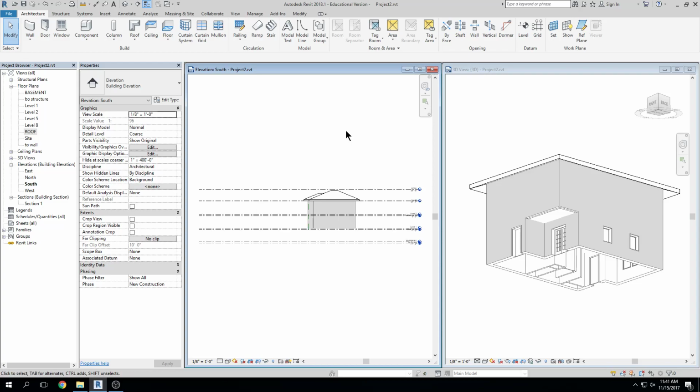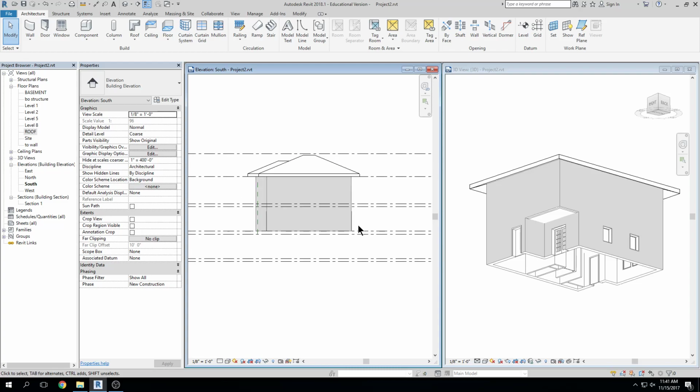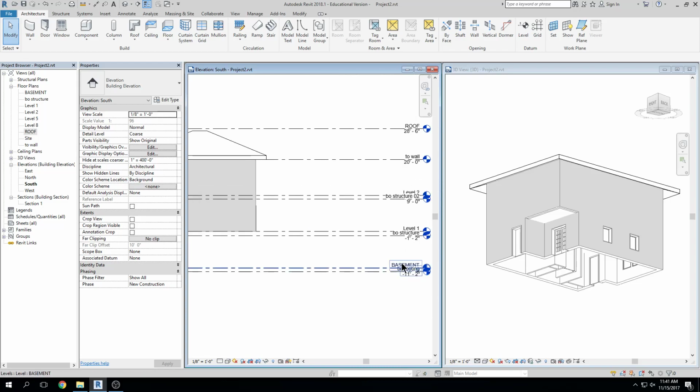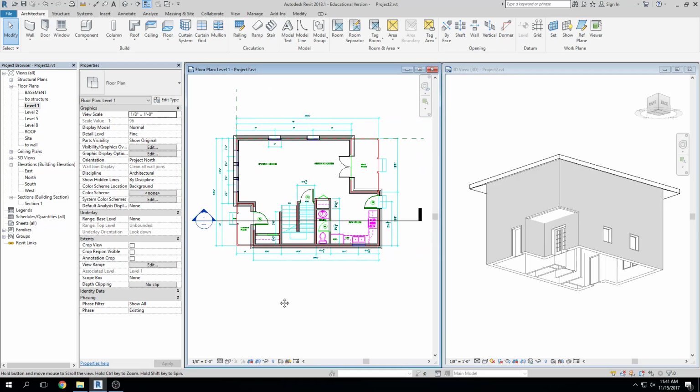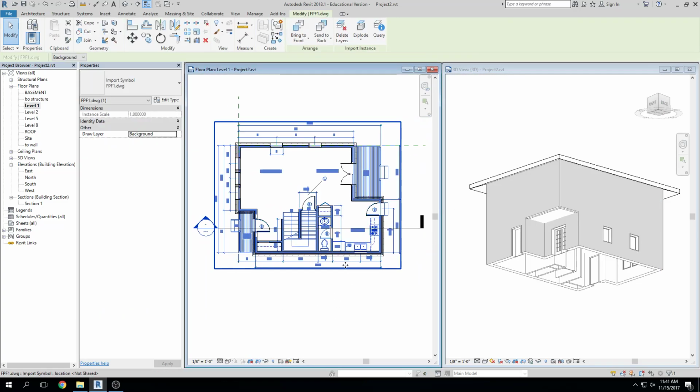Okay, so I have my little house here. Let's add some stairs. Okay, and actually let me add the basement first. I'm going to add some foundation walls essentially. Okay, so I'm going to go to level 1. And I like to do this in 3D. At this point, I don't really need my first level CAD file anymore. It's kind of useless to me, right? So you could hide it just in case you are afraid you may need to reference it again. You could also unpin it and delete it. So I can hit unpin and I can hit delete.